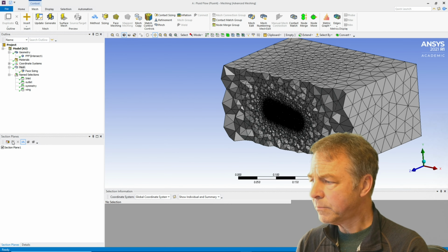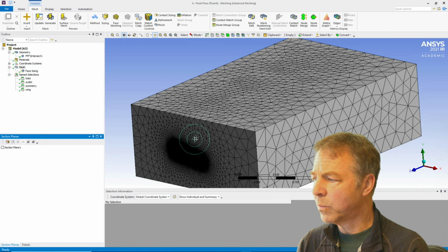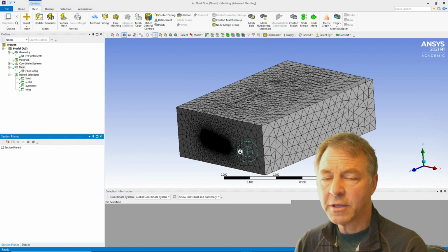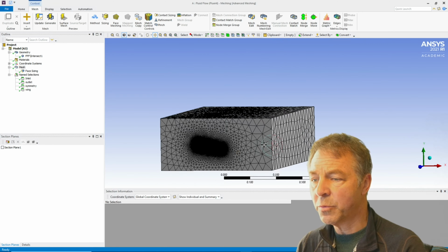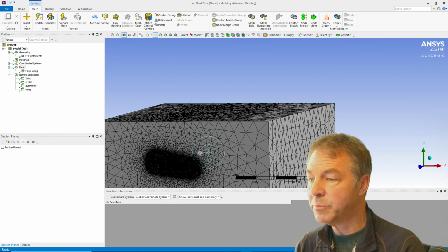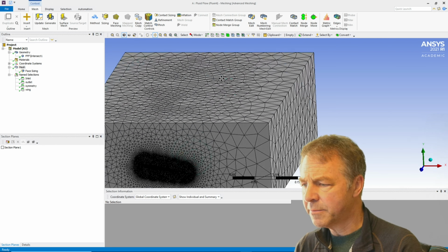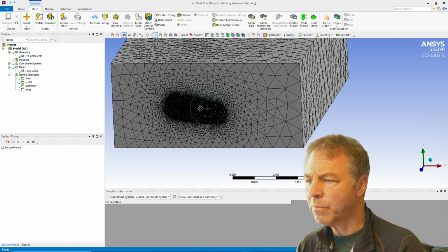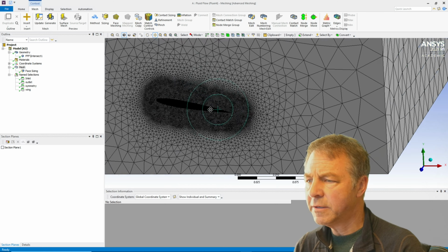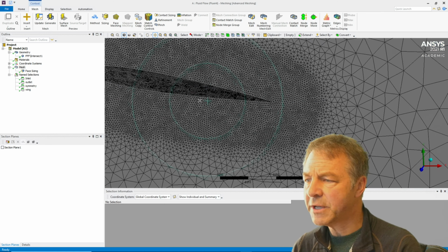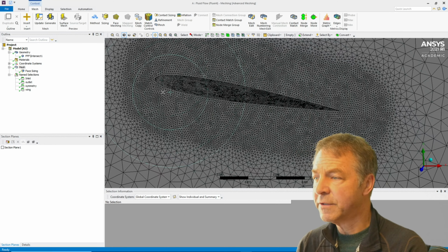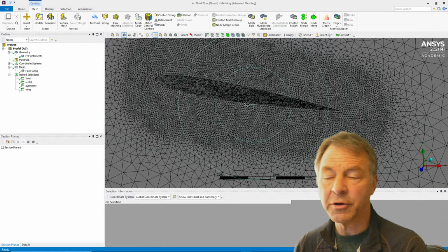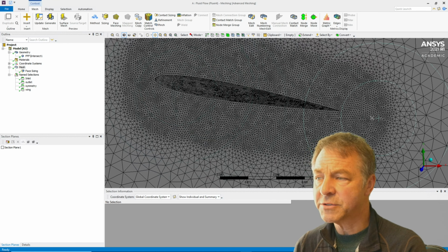And what I simulated was that block, and you can see that I started out with a simple simulation of a reasonable amount of grid elements, and you can see that in order to create a reasonable size mesh, I need to get down to the size of, in this case, a millimeter or half a millimeter of grid point sizes around the wing.